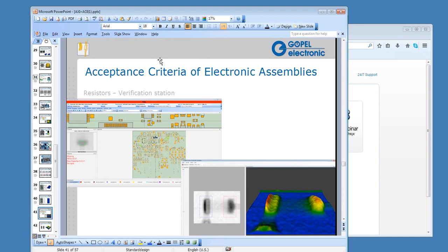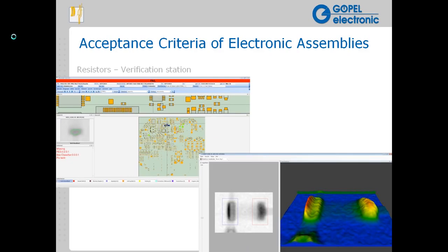To touch on a little bit different subject here, capacitors are a little bit different creature in X-ray. They are very dense and of a material that does not allow transmission of X-rays very effectively. So unlike the resistor example, where you can very clearly see the metallic contacts on the end of the resistor and the body of the resistor itself is largely invisible, in the case of a surface mount capacitor like this, the entire capacitor illustrates its density, so it's a little bit more of a challenge for inspection. The software helps us deal with that.